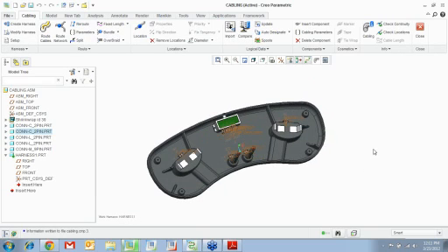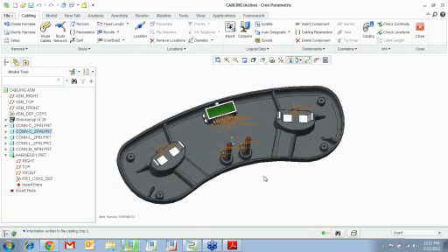Now, once we are at this point, it's about time to create the wire. When you create the wire, you have different routing procedures that you can follow. One of the routing procedures is using a network, right? So I'm going to create a network. A network is like a path that your wire can follow. All right. So I'm going to use a network for a couple of cables. Then I'm going to route them without using the network.